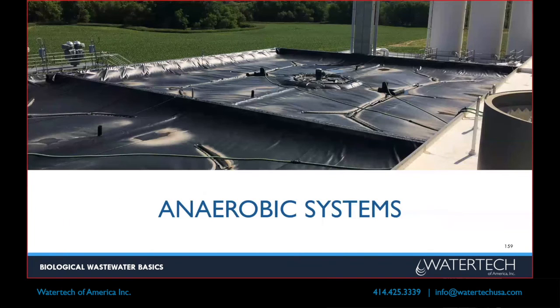So anaerobic, Chris mentioned anaerobic a little bit earlier. Anaerobic means without air. You can tell the difference from that first picture, which had an open top tank, where you saw the brown mixed liquor with the surface aerator mixing it and spraying it around. Anaerobic, Chris, I think, showed a picture of a tank with a dome top on it. This is a picture of a facility that we have where they just have a flexible membrane cover. This is what they call a downdraft mixer, kind of like a boat propeller, that just forces things down and keeps it circulating this way.